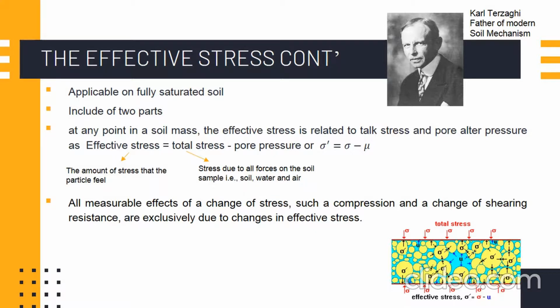It has this equation where effective stress, which is the amount of stress that the particles feel, equals total stress, which is the stress due to all forces on the soil sample, minus the pore pressure. The second part concludes that the compression of engineering components and the shearing resistance depend exclusively only on the changes of effective stress.